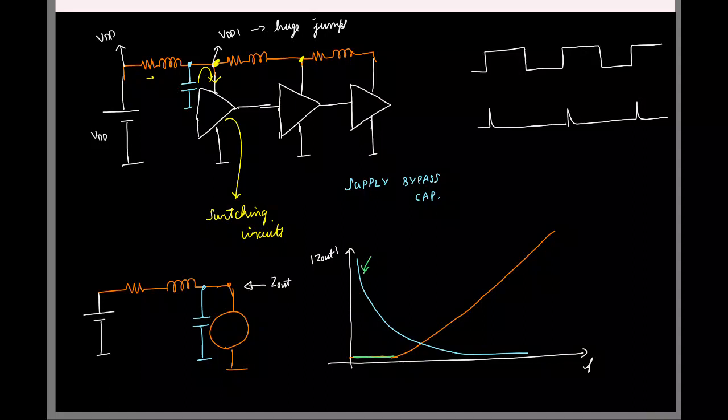And at very high frequencies, what will dominate? The smaller one. The capacitor is going to dominate like this. So in between you will have probably something like this. Just a rough sketch, right? So now we can clearly see, right? Earlier the impedance was actually increasing as you kept increasing frequency. Now the moment you added the capacitor, overall you see that the impedance is actually relatively small across the entire